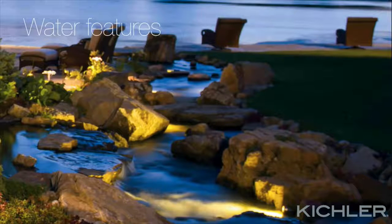There are a few things to keep in mind when placing fixtures in and around water. First of all, make sure that any landscape lighting fixtures around pools or spas are located at least 10 feet from the water. Landscape lighting transformers are not designed for lighting within 10 feet of water that people might be swimming in. There are special underwater fixtures for reflecting pools, ponds, and other decorative water features.